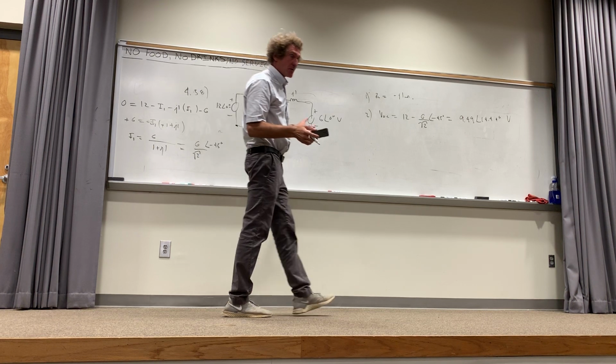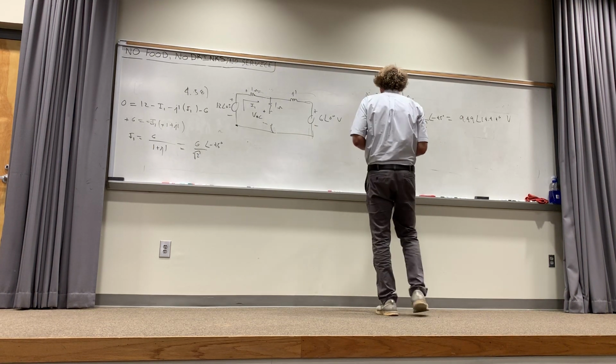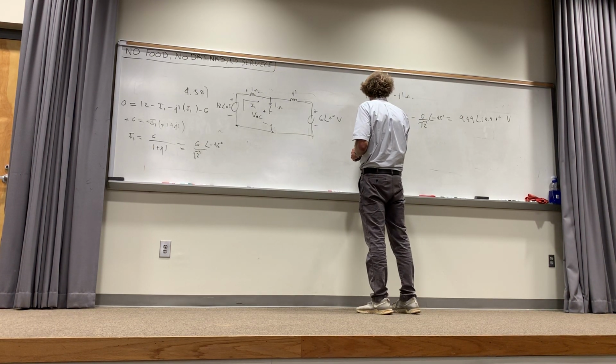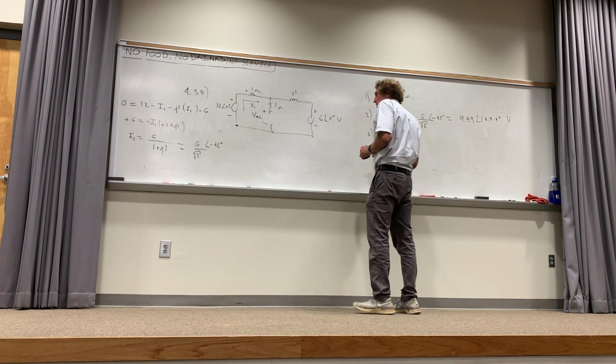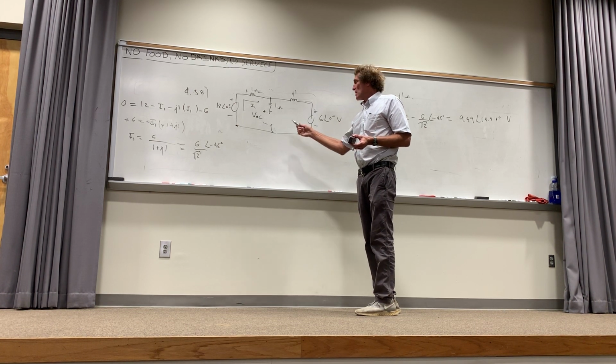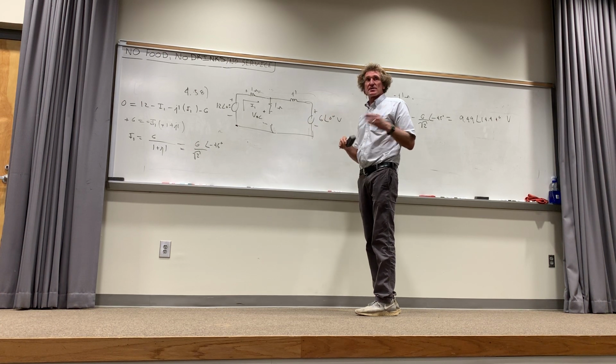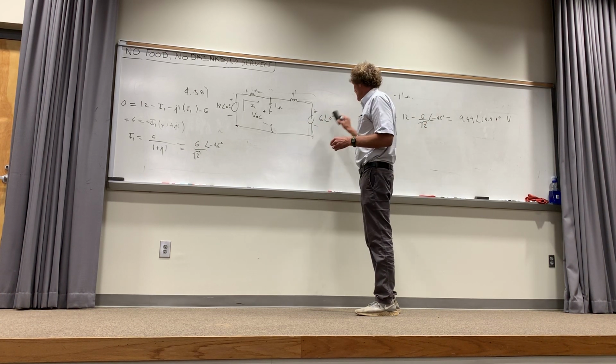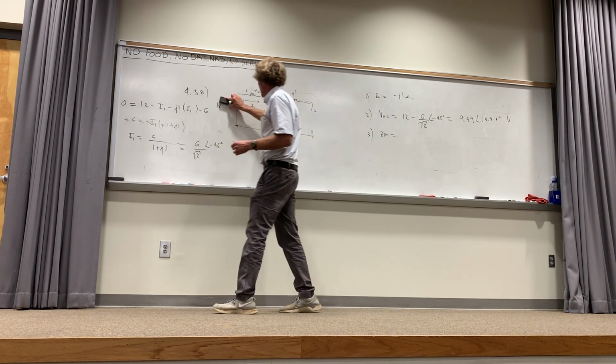So I've got that, and the third thing, right? Now I have to find Z Thevenin. What is Z Thevenin here, class? See, this is a little more complicated, right? What's Z Thevenin? Well, what do I do with these sources to get Z Thevenin, people? Turn them off. Yeah, but we better make sure they're turned on.